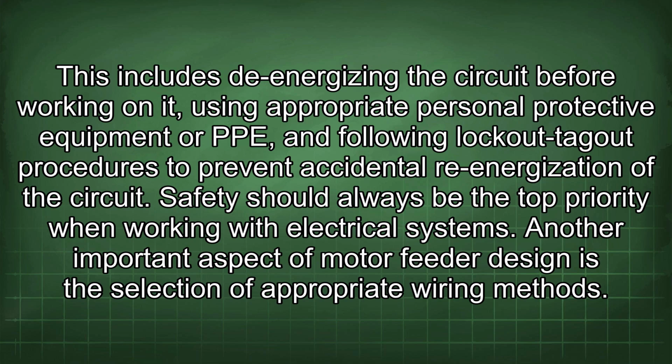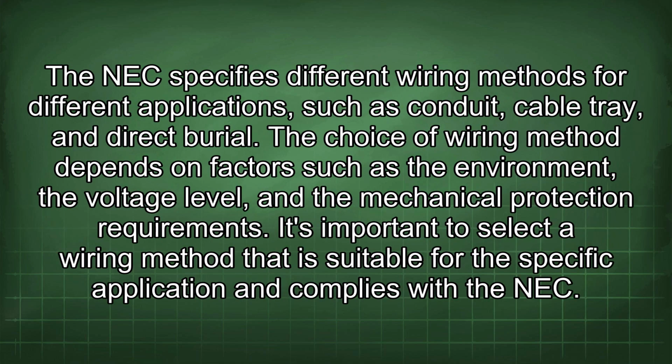Another important aspect of motor feeder design is the selection of appropriate wiring methods. The NEC specifies different wiring methods for different applications such as conduit, cable tray, and direct burial. The choice of wiring method depends on factors such as the environment, the voltage level, and the mechanical protection requirements. It's important to select a wiring method that is suitable for the specific application and complies with the NEC.